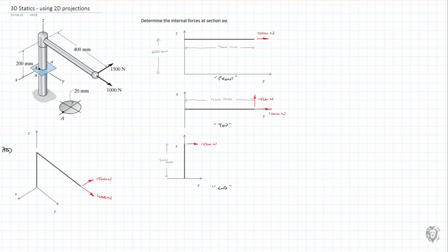And we'll use a very classic partial free body diagram. But to assist us, we're also going to break this down into three planar views. So really a front view, a top view, and an end view, if you want to think of it that way, or the ZY plane, the XY plane, and the ZX plane. And I've drawn those out here to try to help us see what these various component forces are going to do at our plane. And so let's look at them.